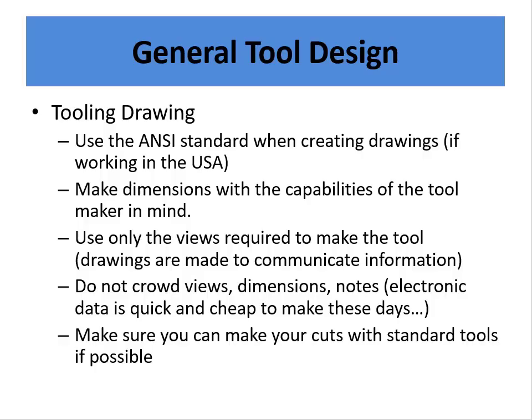But let's say you work at a place where you make fixtures for parts that are made on mills and lathes, and you have some toolmakers running knee mills and that sort of thing. Then maybe you have a wire EDM here or there. You're going to see dimensions somewhere in the thousandths to the tens of thousandths of an inch, and maybe occasionally you see 50 millionths or something like that. But in general, it's going to be somewhere in that range, and that's what you're going to put on your print.